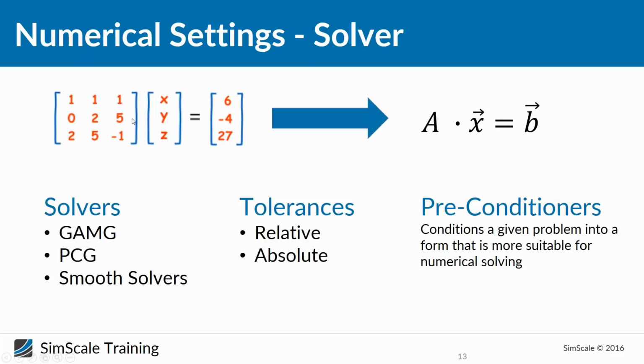And it's the same for our CFD calculation. You know this matrix A as well as this vector B were calculated during the meshing and this integration step. And now we want to know x, y, and z. And for our CFD simulation, in this vector, you will find for all the points velocity or pressure, and then it's again time dependent. But basically that's the idea. So what we want to get is a vector with components x, y, z, which is solving this equation system.